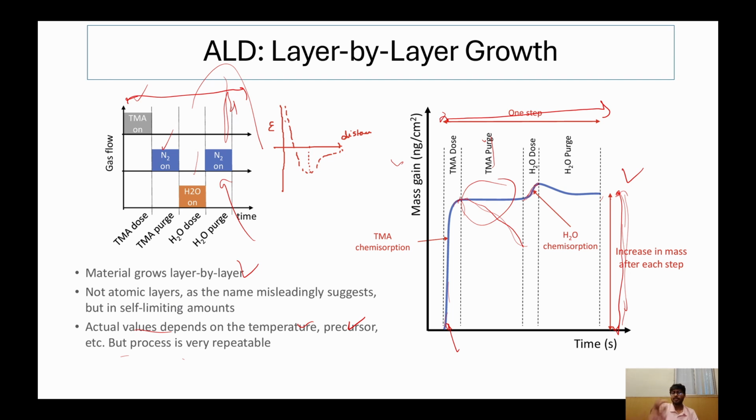You just need two precursors, two bubblers, a chamber, MFCs, and controlling valves, so that you can control those valves through software with some kind of controlling unit. You can make these kinds of things in any lab. Controlling is a bit difficult, but still manageable.